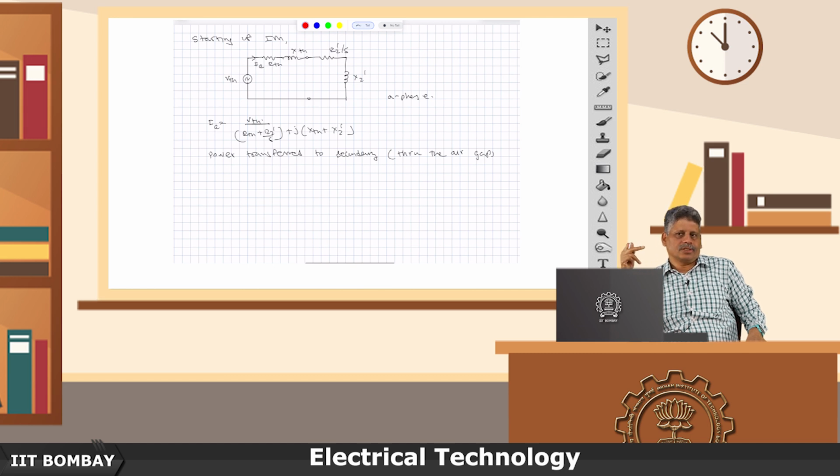The frequency of the rotor currents plus the frequency associated with the rotation, multiplied by the number of pole pairs, should finally translate to what is seen on the primary side, which is our 50 hertz or 60 hertz supply frequency.